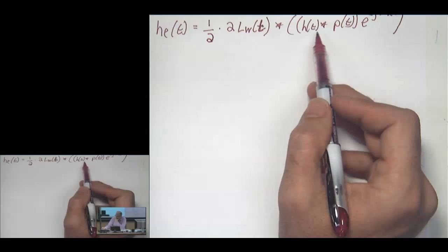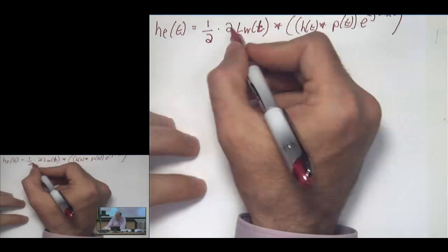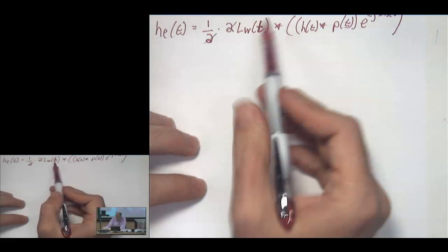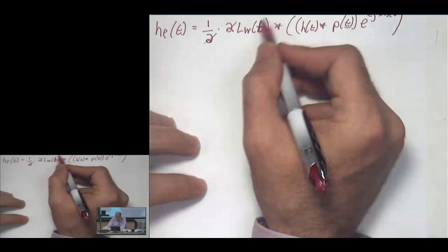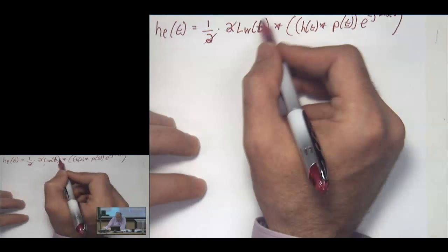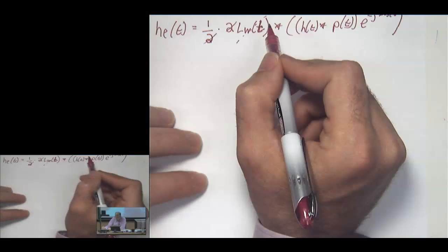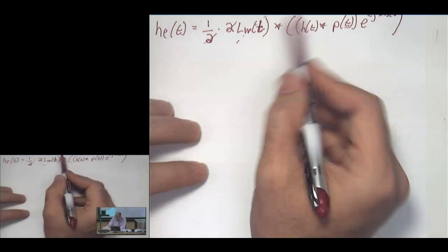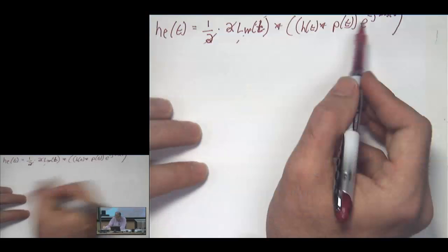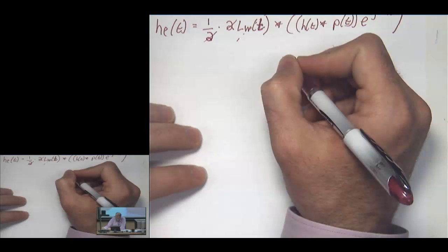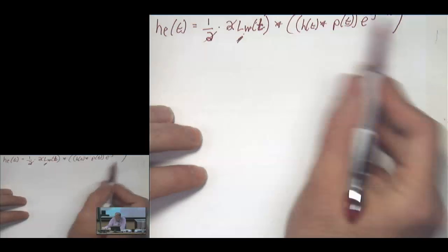And then the things to be careful about here. If you've done everything correctly, first of all, the 2's cancel. And second, when you low-pass filter this signal that's already been passband filtered, that will actually cancel as well. So for all practical purposes, this goes away. But I shouldn't take it away really, because you need it to get rid of this effective carrier here, but it won't show up in the final expression. But that's essentially the formula here. So low-pass filter convolved with this whole thing right here.